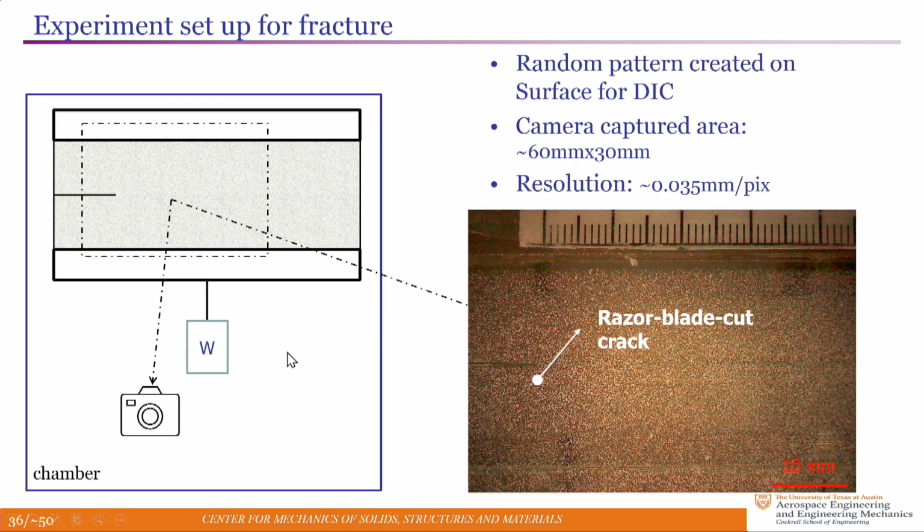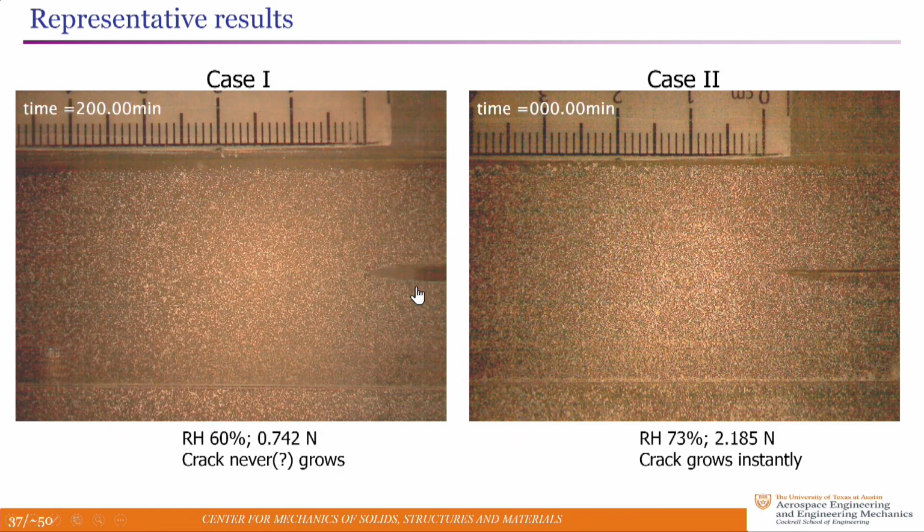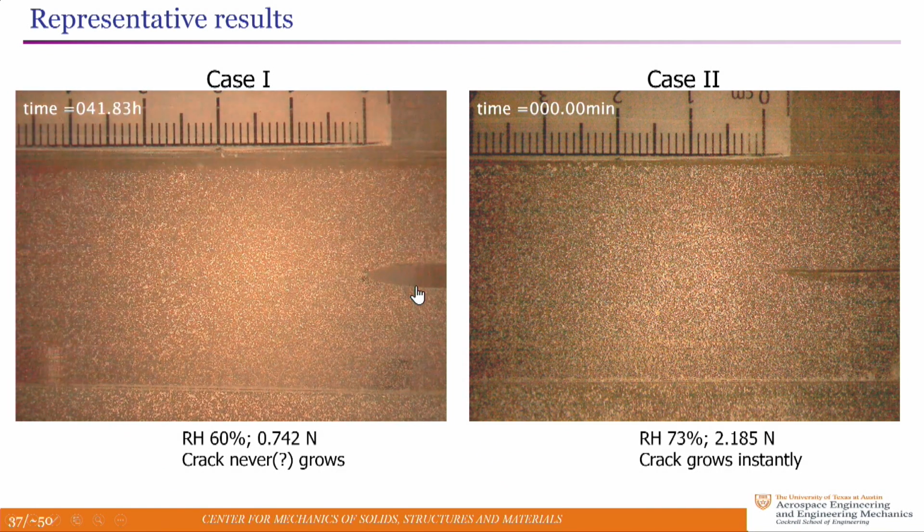We decorated the specimen with these titanium dioxide particles, and you can see what happens. So I'm going to distinguish between a number of different cases of loading. They're all constant humidity environment, dead weight loading. But in this case, the relative humidity was smaller than the equilibrium humidity of the specimen. And so the specimen is going to dry over time. And if I load it, there's an instantaneous elastic response. There's some creep.